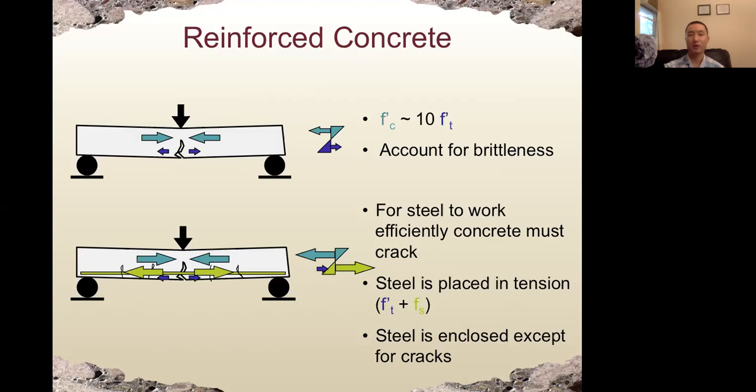Okay, so when we put in the steel reinforcement, let's see the bottom picture. On the bottom of the steel reinforced beam, which is the green line here, steel is very strong under tension. So the moment the steel reinforced concrete beam can resist will be much higher compared to a plain concrete beam.